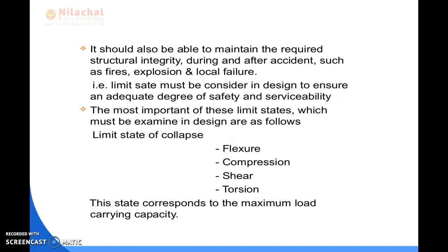It should also be able to maintain the required structural integrity during and after accidents such as fire, explosion, and local failure. That is, limit states must be considered in design to ensure an adequate degree of safety and serviceability for a structure. The most important limit states which must be examined in design are as follows.